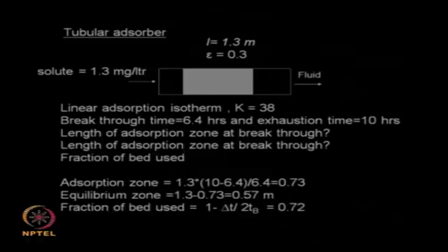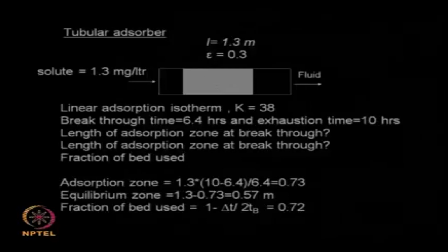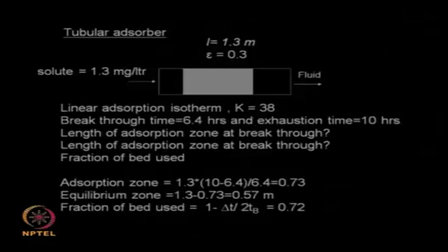at the breakthrough point, and here in this particular problem we find out that 72% of the bed is used up when the breakthrough happens. That means 28% of the bed is not used up, but still you will stop the adsorption process and regenerate your material.